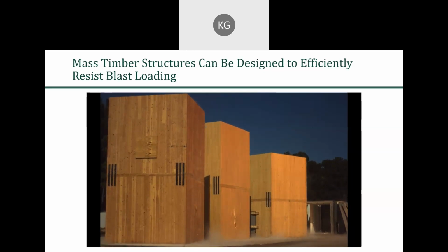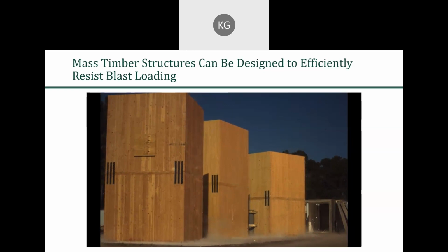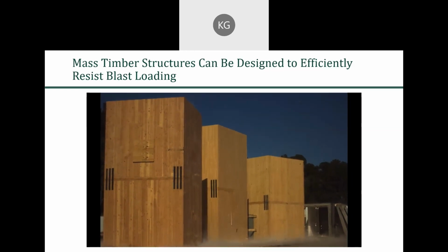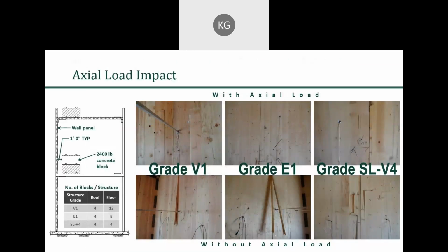So the main takeaways were that mass timber structures can be designed to resist blast loading. They actually perform rather well. And that the rebound response must be considered for both the panel and the connection design. Question: by rebound, do you mean the negative pressure wave? Yeah, yeah.